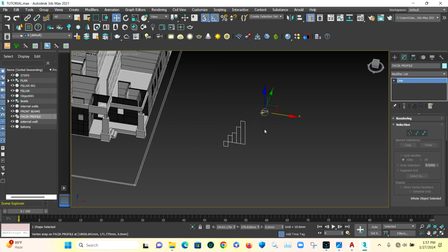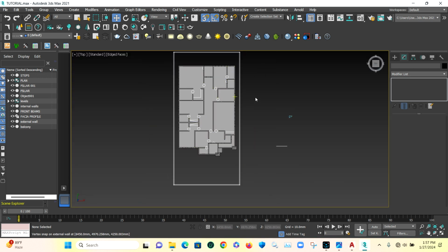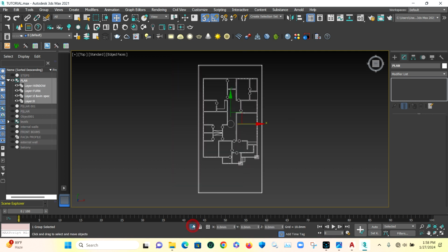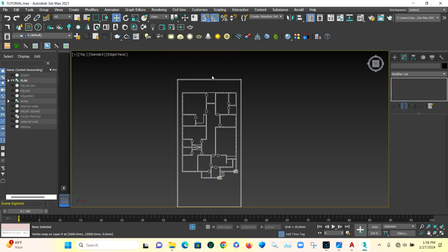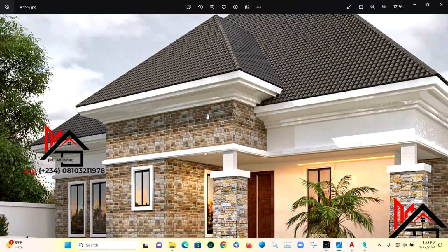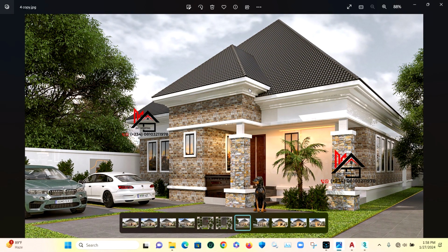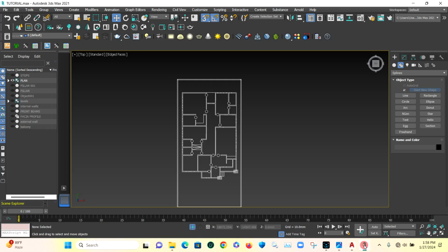Now what do I need to do again? The next thing I need to do is to select my profile. This is my parapet. Where will it go? The point it will go in this drawing. Now I can do that with this or with just the floor plan. So I can just bring out the floor plan, since with this I'm already seeing where the parapet will go. Remember from this drawing that this parapet and this one are of different heights. Remember, don't forget. So when we get here now, I'll use my line command.